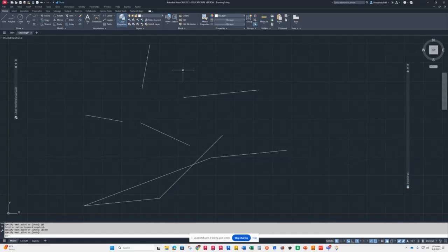All right. It's almost lunchtime, so I think that's a good spot to stop. Like I said, on the polar, I turned ortho off because I don't want to use it. You can't have ortho and polar on at the same time. So use the one that looks like a little duck there. Then you can click the little down arrow next to any of those boxes to get options. For this one, and I'm almost done, I have mine set on 15, 30, 45, 60.